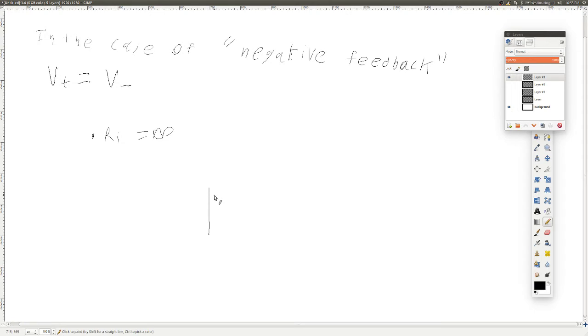An op-amp, as we talked about a moment ago, has two ports, a minus terminal and a plus terminal. When we said earlier that Vx, which we'll now go ahead and change, so we can scribble that out and say Vout, since we know that RO can be assumed to be 0, Vout is equal to A times V plus minus V minus. If V plus and V minus were anything other than 0, because of the fact that gain is infinite, the output would be infinite. So this equation actually really becomes useless. But it does tell us something. For any case where V plus isn't equal to V minus, the solution to this circuit is trivial. It's infinite. And that's not possible.